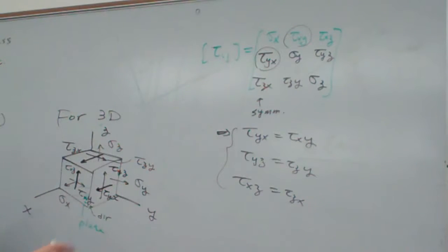That is due to static equilibrium. For the three-dimensional case, the general 9 components won't be 0. For these situations, hopefully I can show you the fundamental concepts of how to do the transformation of the stress. This is the most general case, and we didn't talk about it in mechanics of materials.